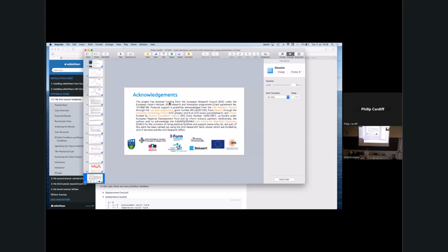This is for the quasi-Newton, the IQN. I'm pretty sure the implementation, which I didn't write, may have been Joris de Groote's implementation in foam-extend, his old version anyway. Then I think Željko Tukovic took it into foam-extend, and then that was taken and put into this. That has a reuse flag, which sets the number of previous interface fields used to try to guess the new field. So yes, it's there.